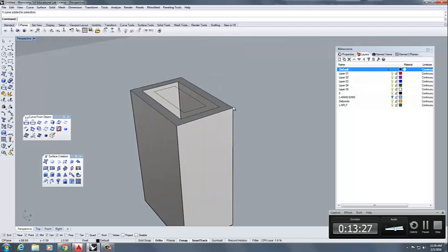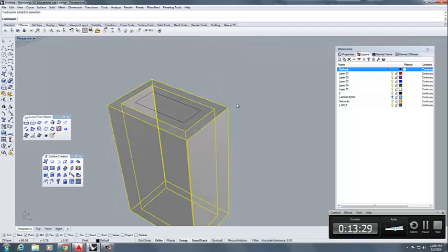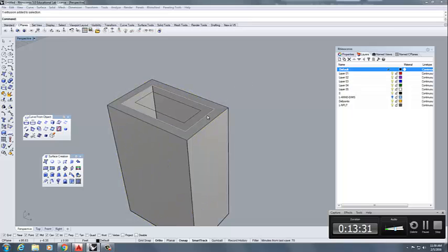Now, let's move this down to a distance that makes sense for us for the bench height. Well, let's create a surface first. We've got these polylines right here, so let's select these two polylines. We hold Shift, select those two, and use the command that we already used, the surface from planar curves. We've got to create a surface. This is for the seat. Okay, we got a new surface. Cool, that's one way to do it. We can do lots of different ways.